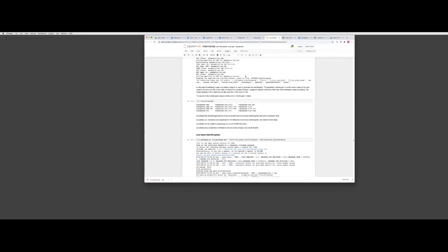The result of this step is in the interferogram directory. topophase.amplitude is the amplitude of the interferogram, probably the correlation, and .full means it's at the full resolution. topophase.flat is the interferogram corrected for topographic phase, and that's what we want to take a look at.